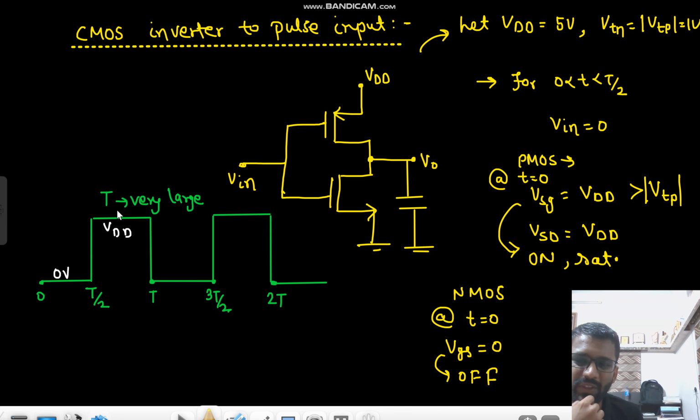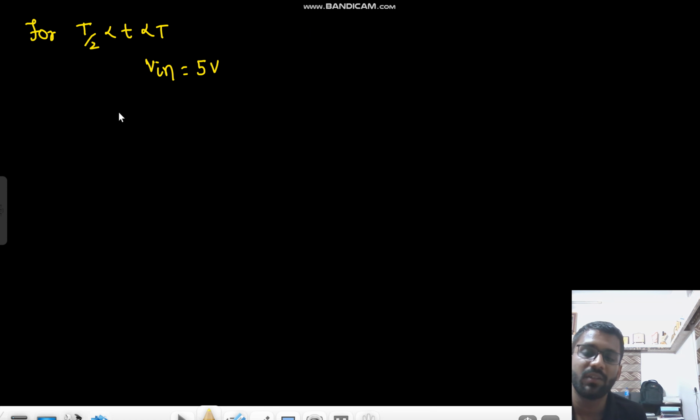Now for T by 2 to time T, your V in is VDD, that means V in is 5 volt. So now for PMOS, your VSG is 0 volt.